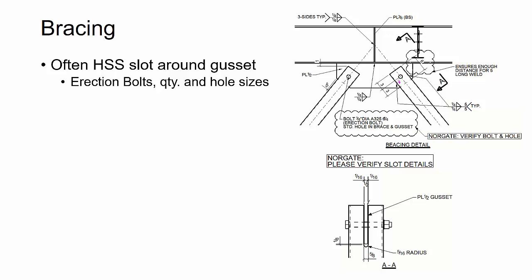And you'll also want to ask what grade of bolt is used. Oftentimes for these braces, especially if only one bolt's being used, I'll still provide a structural bolt there, like an A325 bolt. But sometimes A307 bolts will meet the capacity and work, especially because these longer bolts start to get a little bit more expensive. So always worth asking the fabricator and erector.